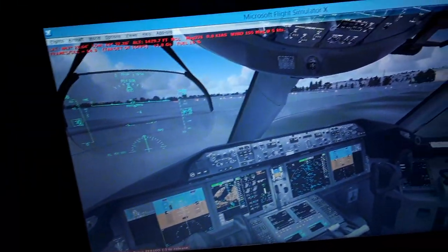We also have in the navigation display the navigation aids, the radio stations, NDBs and VORs, and the waypoints, which are horizontal and vertical navigation fixes, and also the airspeed constraints. You're going to select some waypoints from the flight management computer. You're going to see how later when we create the flight plan. They show us a purple line connecting the waypoints one by one. That is the flight plan. We have to follow the route of the aircraft using the autopilot or manually.